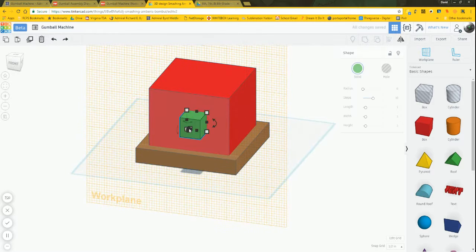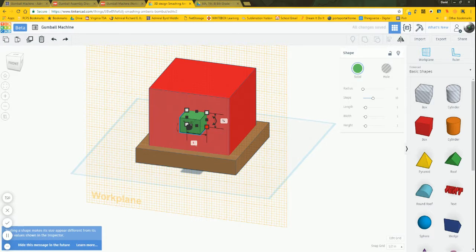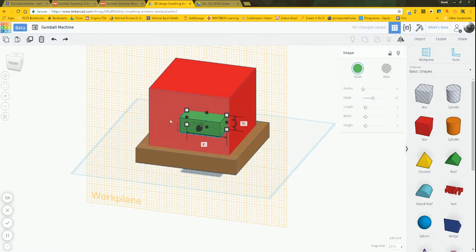Okay, so we said that the height of our slot would be 0.75, like all the other parts. Our width was going to be 2 inches. And I could actually set it like we did here a few minutes ago. I can put it in the upper corner and use the snap grid to move it from there. I'm going to go to a 16th for now and just zip on over towards that upper corner.